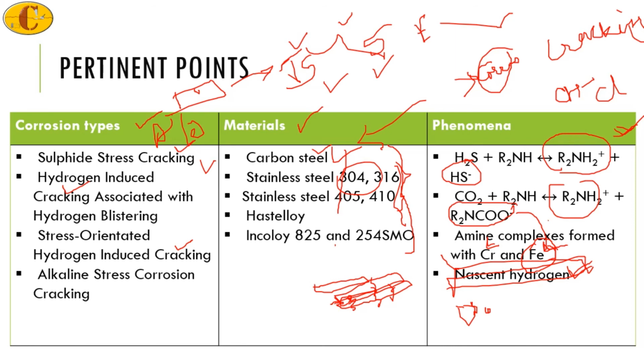So then the materials which are recommended are, in this case, exposed to the environment, such as hydrogen sulfide dissolved in water, where you have the formation of nascent hydrogen. The quantity of hydrogen taken up by these materials is calculated, and the effect of this hydrogen taken up is then measured in terms of how much the tensile stress is reduced due to the hydrogen. So that is one way in which the recommendation of these materials in the standards is done.